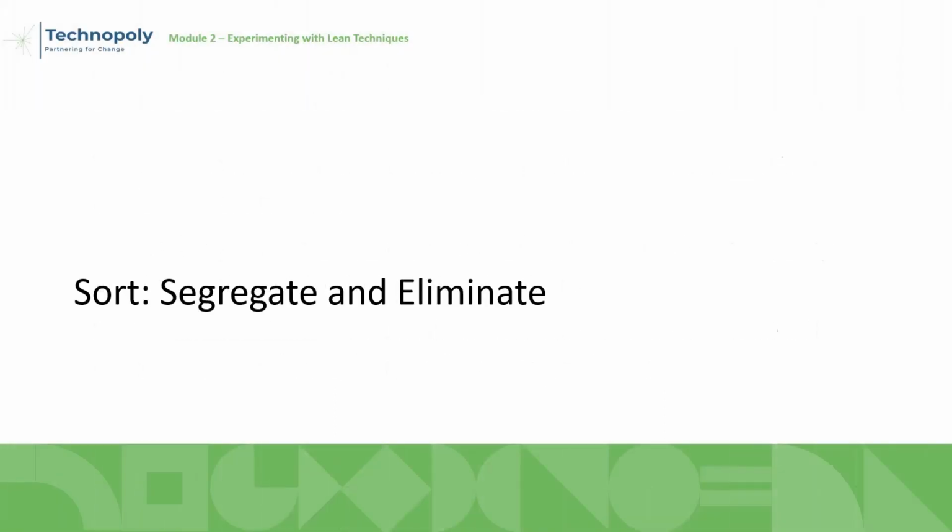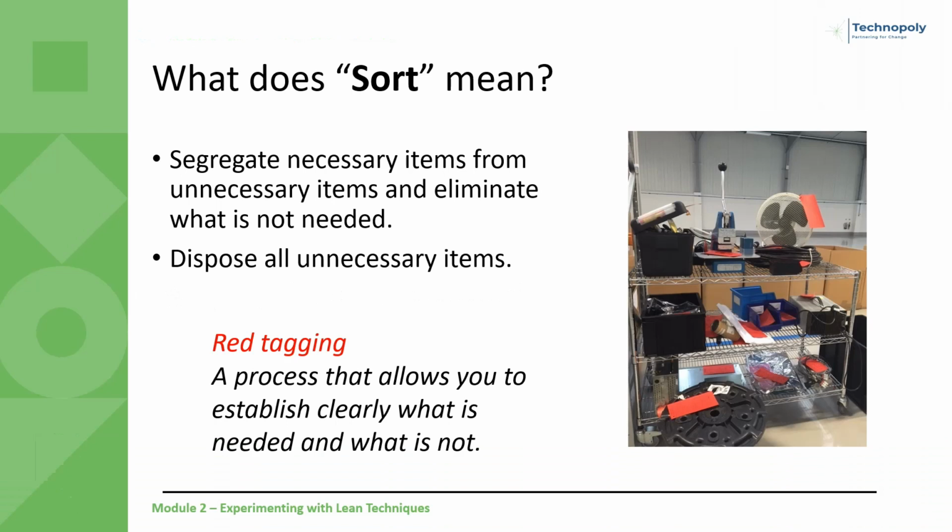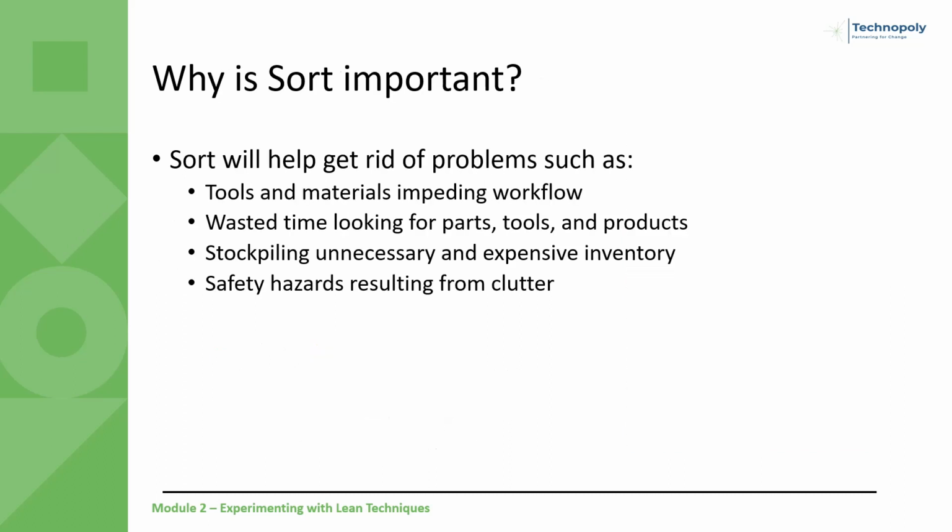The first of the 5S is sort. The goal is to eliminate all unneeded tools and materials and create a space free of clutter. Sort is a two-part process in which employees identify what is not needed and managers and supervisors take responsibility for disposition of those items. This is often called red tagging because it calls for a simple red tag to be placed on items that are not needed for work. Keeping only essential items leads to fewer hazards and less clutter.